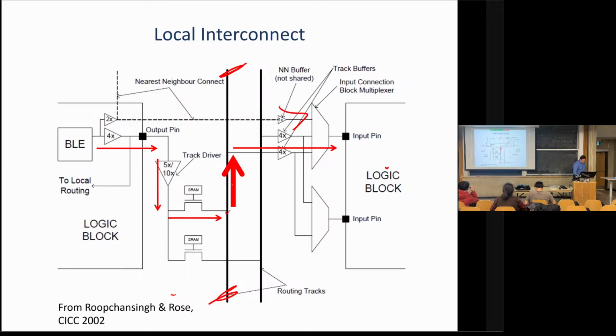And normally I would still have this, right? I'd have some tri-state buffers or a direct drive mux. So they got rid of one more level of muxing versus having that, and they got rid of this capacitance. And if you didn't have really short wires like that, then they got rid of more capacitance.